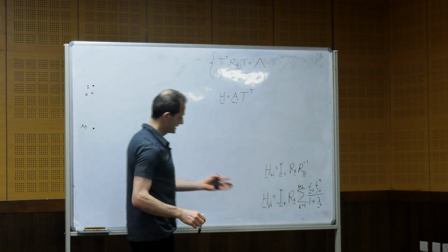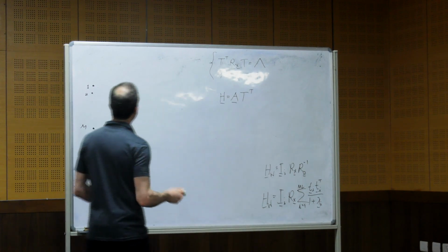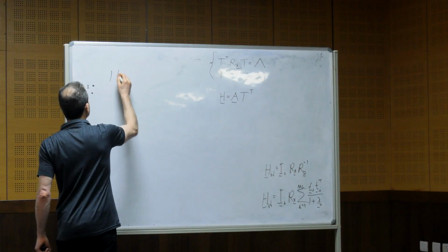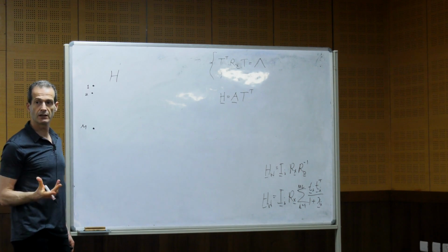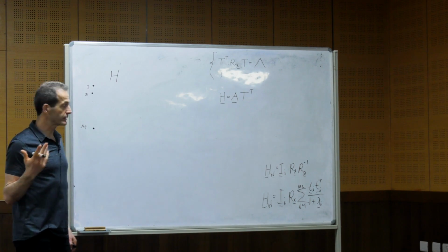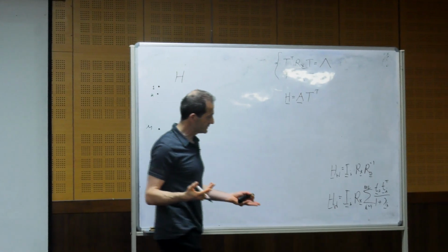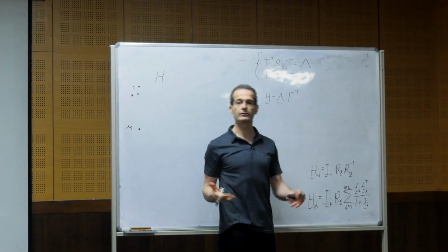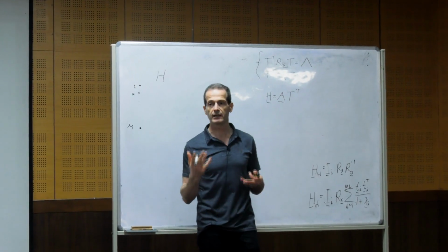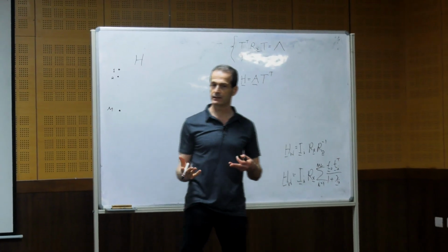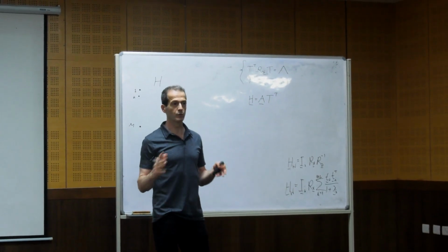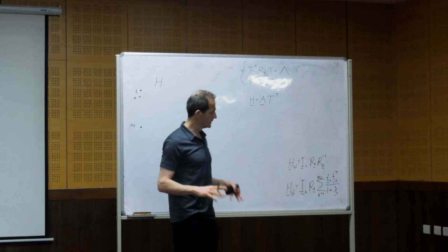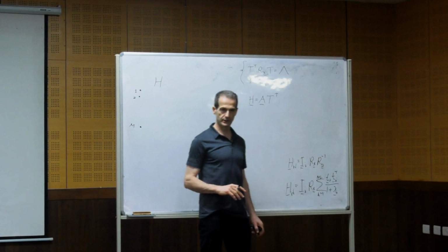From this expression, we found an alternative way. With the Wiener filtering matrix, we don't have a trade-off to control the signal distortion and the noise reduction, because we just minimize the mean squared error.